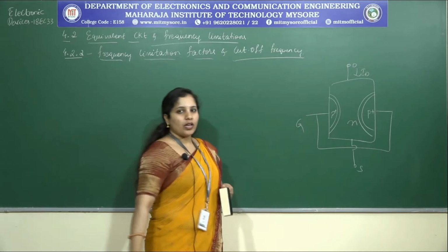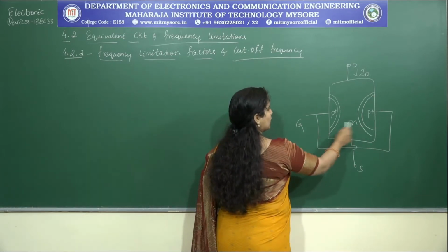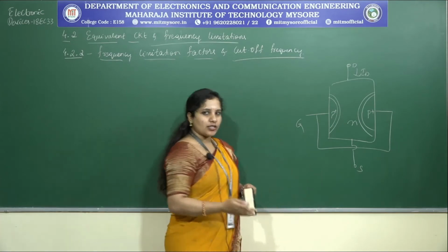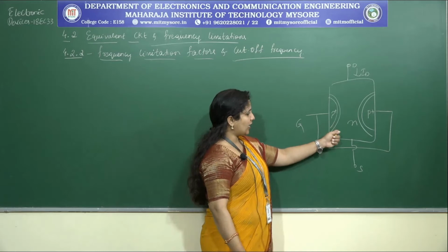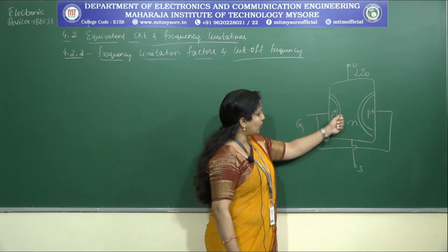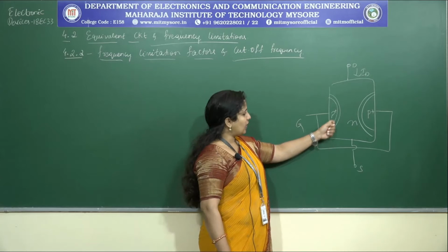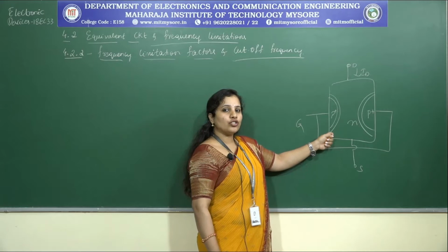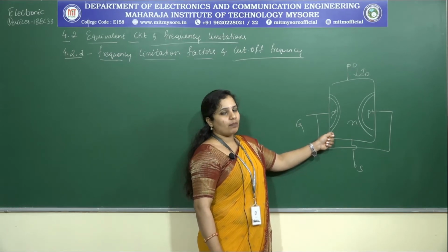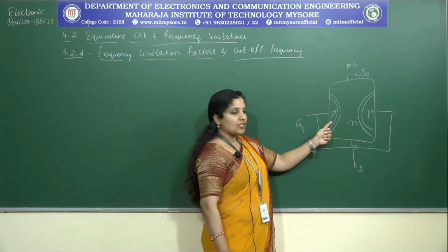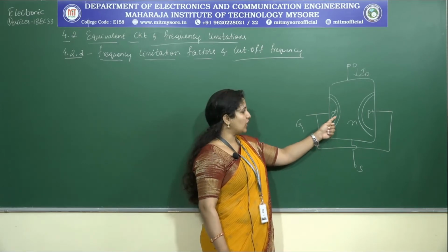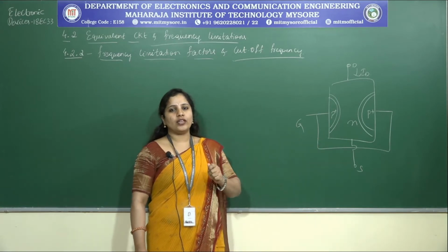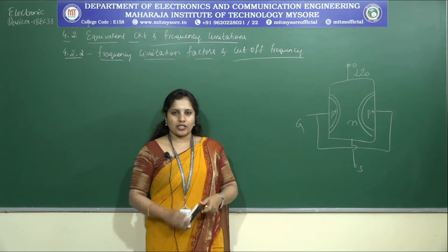this is your structure. Now, what are these regions? These are the depletion regions. Now, if I want to represent, there is a capacitance behavior that exists between the gate and the source. What does that basically indicate? We have a depletion region in between, and then we have accumulation of charge carriers in this region and in this region, which in turn makes it behave as a capacitor. Done. Now, will there be a certain amount of time required for these charge carriers to get accumulated? Yes, and that is what we refer to as the charging time of the capacitor.